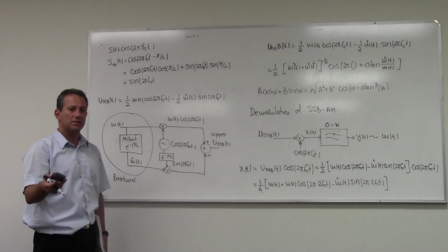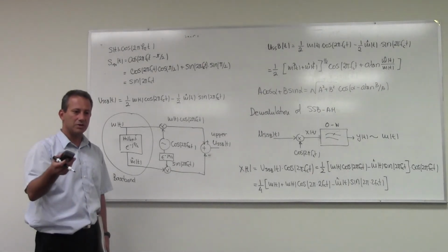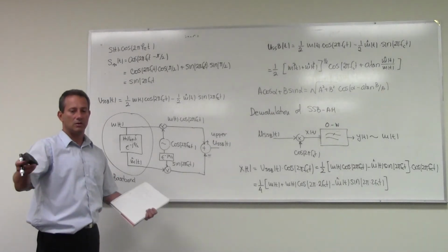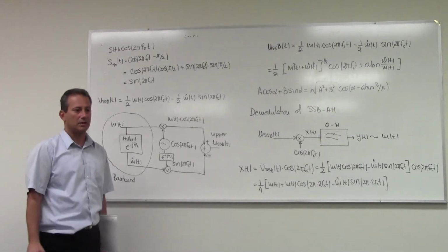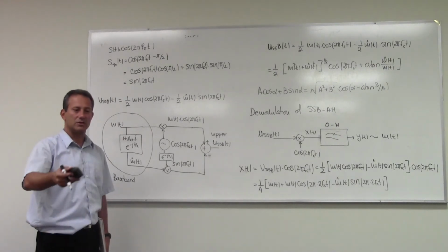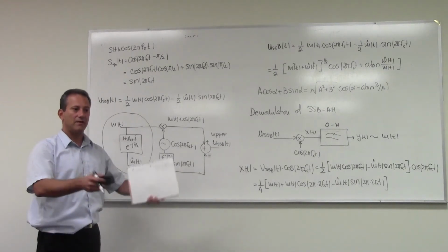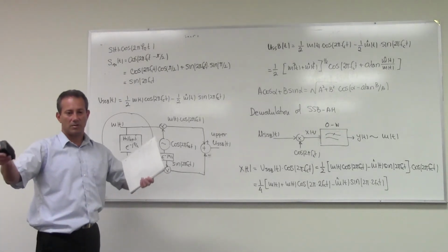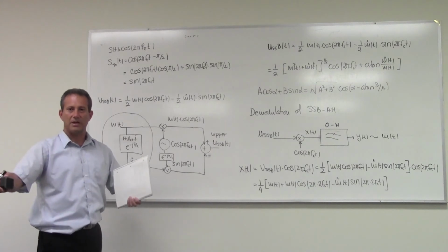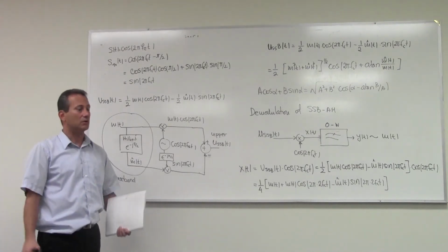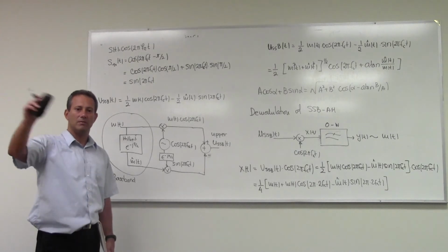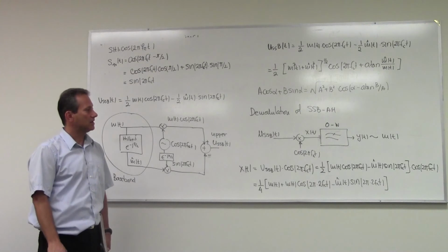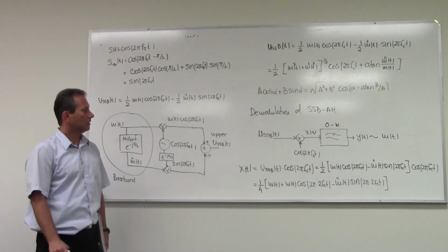We said there are two principal reasons why we modulate. One is to adjust the properties of the signal to those of the medium. The medium, which is the physical reality through which the signals travel, can have properties that favor one frequency band over the other. If you're transmitting through lines, then you want to be closer to the baseband or to some cutoff frequencies. If you're doing it wirelessly, then you want to be much higher in a frequency band, because then you can have reasonable size antennas and other requirements.